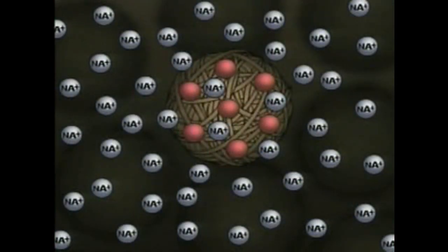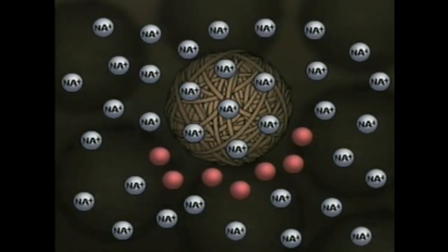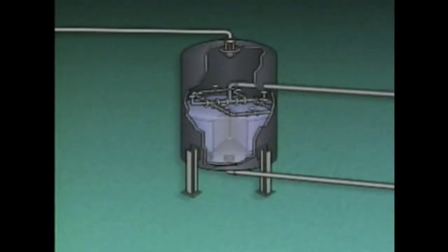The overwhelming number of sodium ions in the salt water solution overcomes selectivity. The sodium ions drive the hard ions off of the resin bead sites and replace them. Finally, in the rinsing step, rinse water enters through the water inlet. Rinsing removes the remainder of the salt solution and the hard ions from the softener. The rinse water drains out of the outlet and is pumped to a treatment facility.